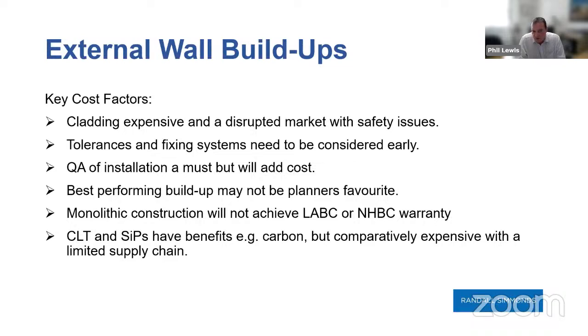Tolerances and fixing systems need to be considered pretty early. How the QA of the installation is performed needs to be included in cost planning. And the biggest thing that sort of upsets me, if you like, is my most efficient build-up might not be the planner's favourite. Just be mindful also that monolithic construction will not achieve LABC or NHBC warranties currently.